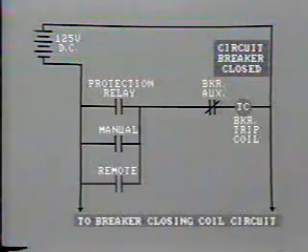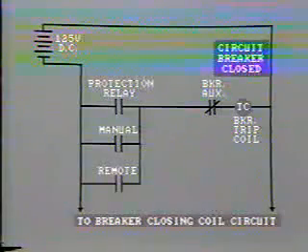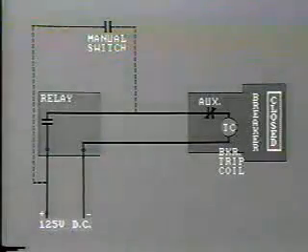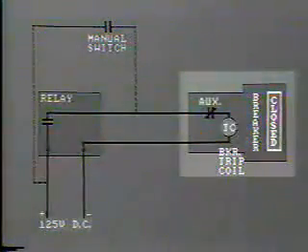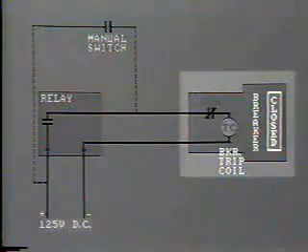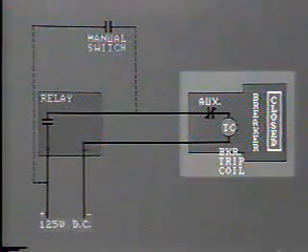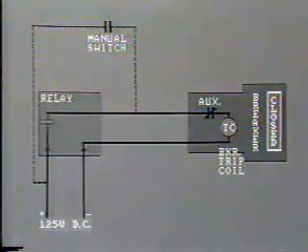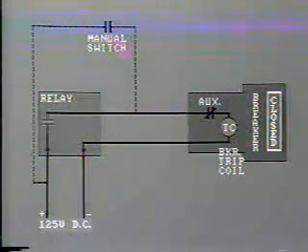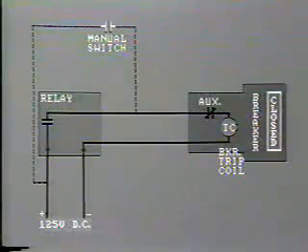In practice, there may be other parallel contacts which can open the breaker. Remember, the circuit breaker tripping coil and its auxiliary contacts are normally located at the circuit breaker inside the cabinet. This is probably in the switch yard, some distance away from the relay panel. However, relay operating contacts are located inside the relay. The manual switching contacts are normally located on the control panel.